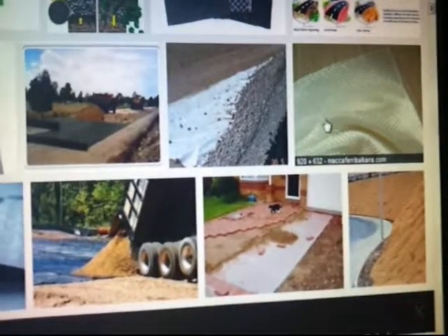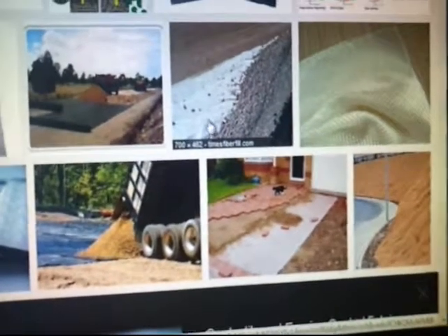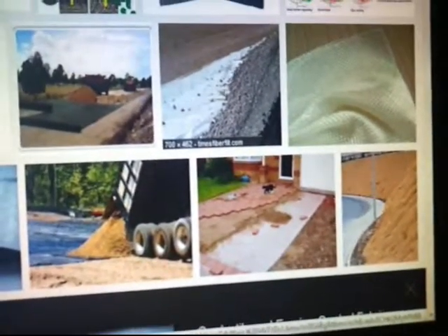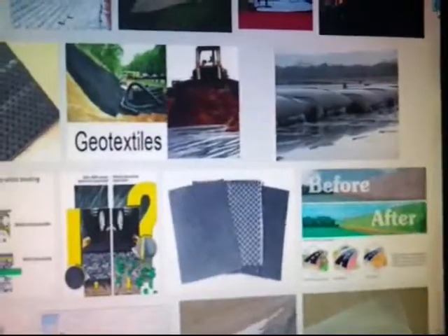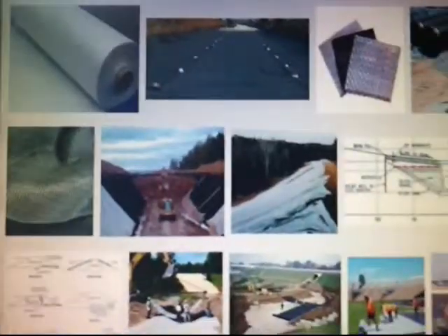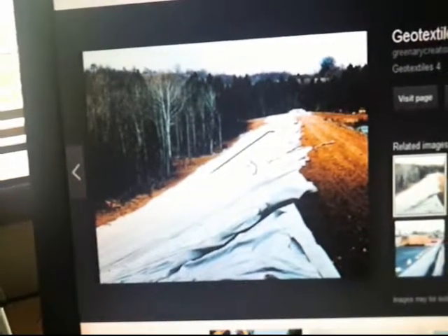Underneath pavers, a sand base, pavers on the top, sand, and underneath the sand the geotextile. Even on large areas, the geotextiles can be woven mats like this, looks a bit like fiberglass being woven, or they can be something that's far more consistent, and they really have a huge impact on soil erosion, and that's probably the most popular usage.